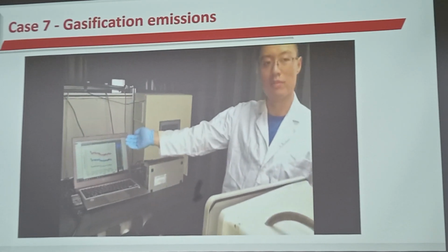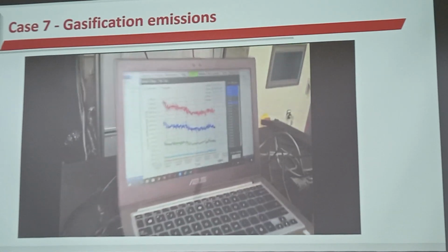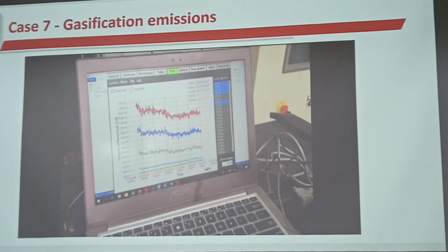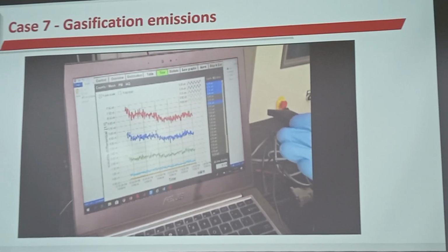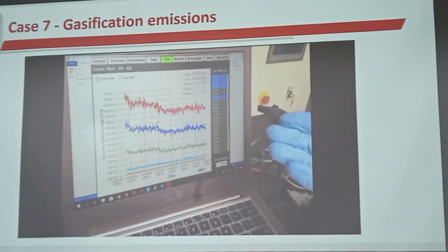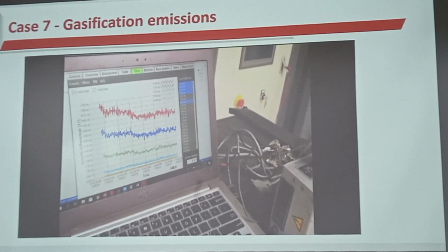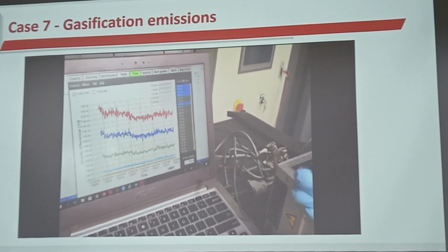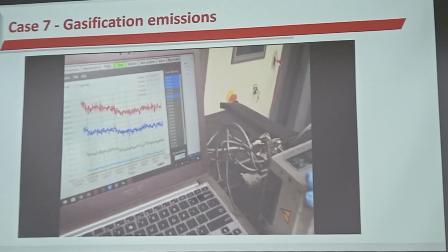As you can see from the control panel, this aerosol spectrometer can monitor the transient size-dependent particle number concentrations. There are 31 size bins in total. We can measure the particle number concentration within the range from 0.25 micrometer to 32 micrometers.